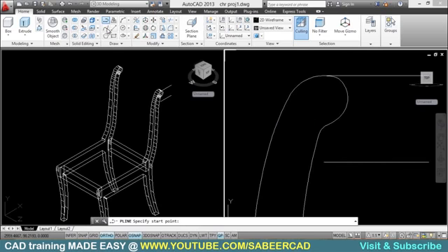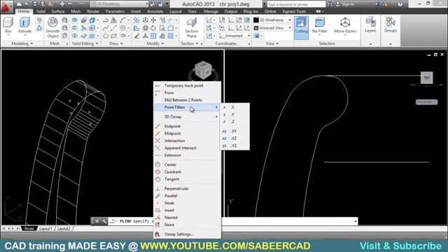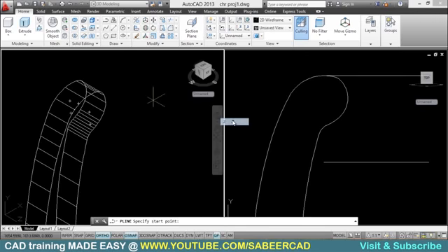So I'll go to the polyline tool and I must start the polyline exactly on this face. So the best method is to use point filters to define the start point of the polyline. So I'll shift right click the mouse to get point filters. If you need any clarifications on point filters, please refer to my exclusive video on this topic. Now I'll select dot Z off. Okay. I'll click on the center point. That means Z is taken from the center point. Hence, the polyline will be drawn on this face.